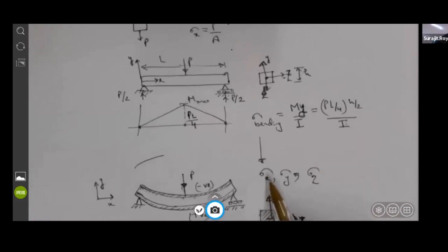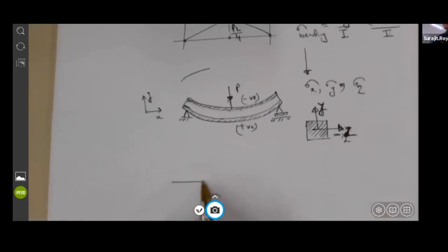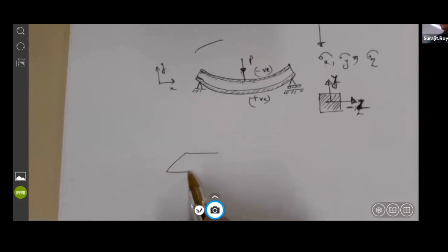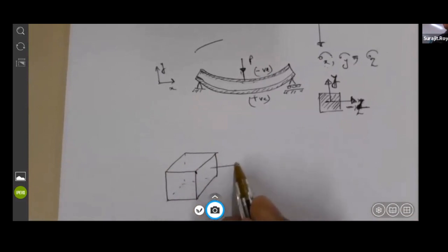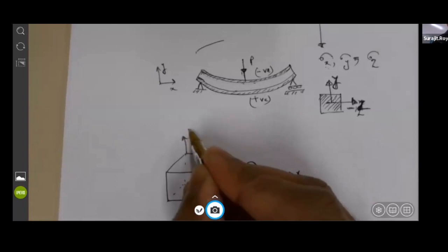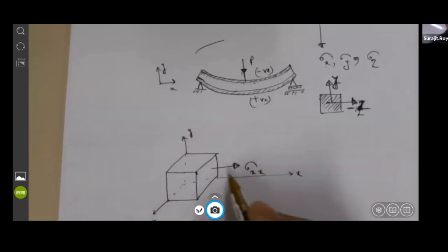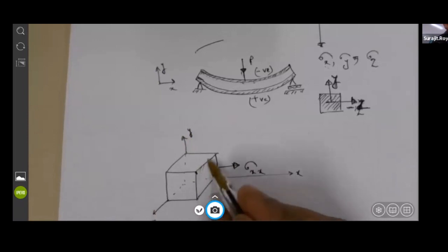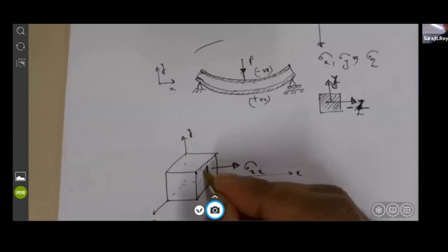The reason I'm insisting you guys have an understanding about this X component is that we will cover this topic in more detail in the next lecture. Stresses at any point in a body are represented along a cuboid, a three-dimensional cube in Cartesian coordinates, where each face has a specific component. Each of the 6 faces of this cube has one normal component and 2 shear stress components.